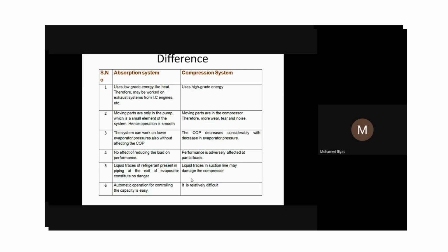No wet vapor should enter into the compressor of a vapor compression system. Because if it enters with moisture, it may affect the mechanical component, and because of some losses our actual COP will be less than that. So we'll compare one with the other, and we'll get the relative COP.